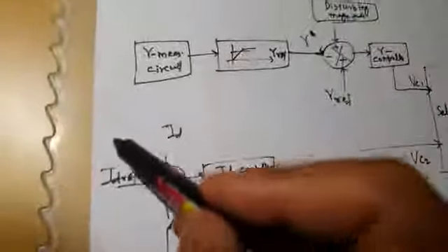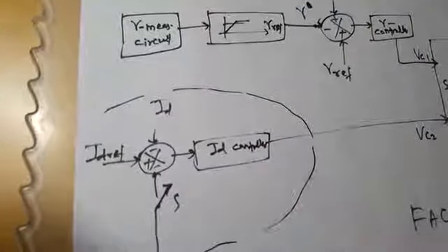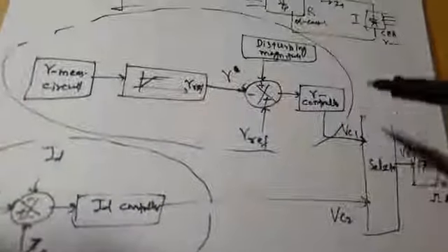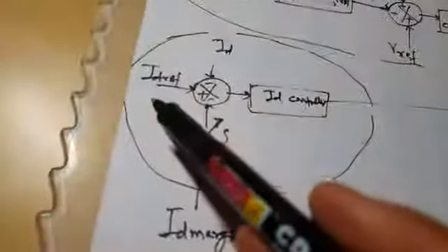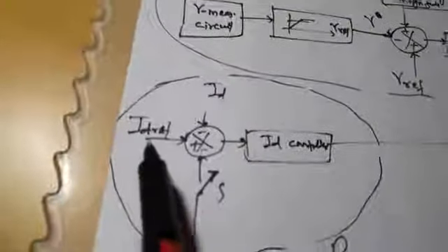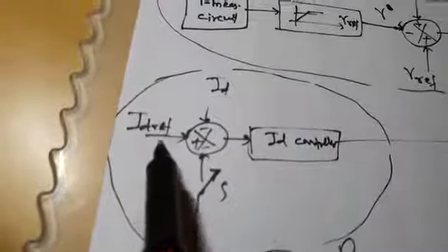Now this is your rectifier control, R, and this is inverter control, I. So now you have two types of controllers. One is gamma control. On inverter you have gamma control, and on rectifier you have current control. Now on the rectifier side, we actually try to maintain the DC line current as constant. So let us suppose DC line current reference value is ID ref, and this is the actual DC line current.